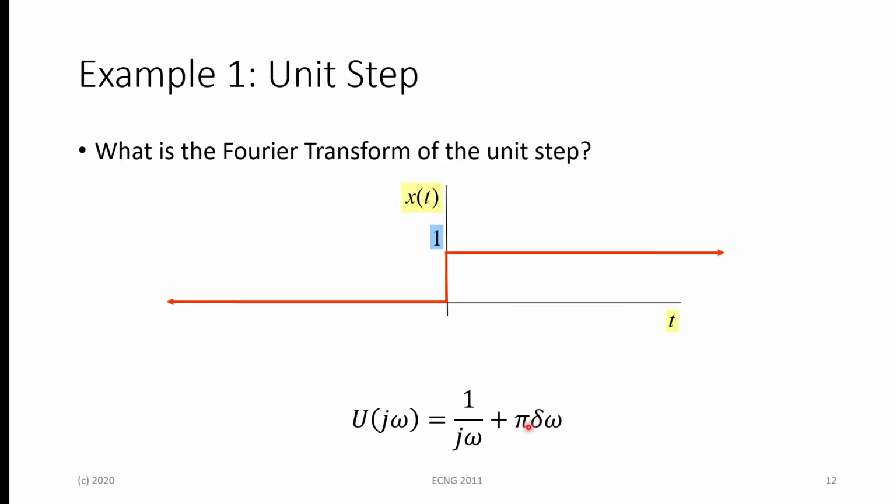And as such, when we plug that into our final equation here for the unit step in the j omega domain, it will equal 1 on j omega, which was our Laplace domain evaluation, plus the Fourier transform of a half, and that evaluation gave us pi delta omega. So in doing the evaluation for the unit step and any other general signal that you may encounter, you can use the Laplace transform to shortcut half of your work for respective values in the Fourier transform.